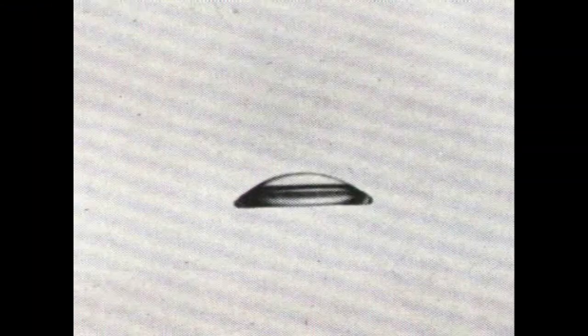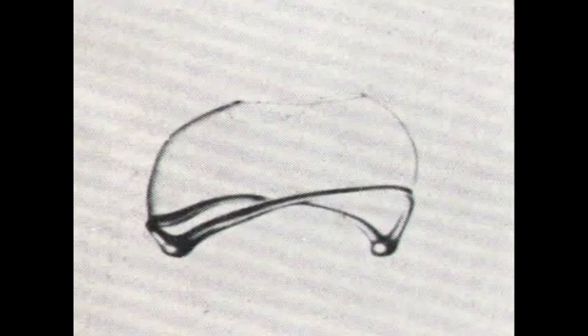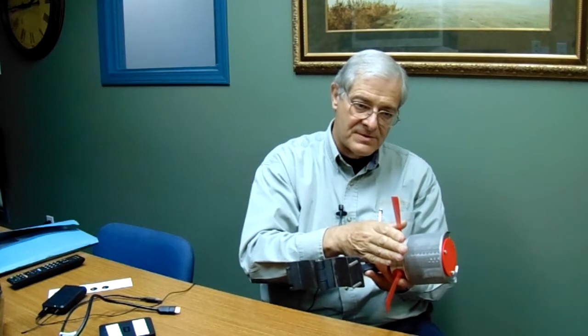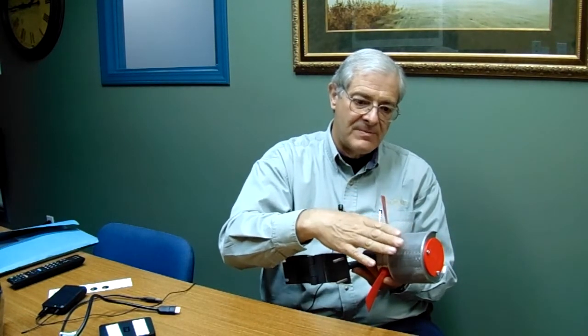And the result can be that the air just literally rips the droplets off as they're being formed, and you get a less good spectrum, and also you tend to get smaller droplets. On the other hand, if the air is deflected away from the gauze, then you're producing the droplets in a regime of much lower axial velocity, and they'll have time to form before they're released into the airflow.